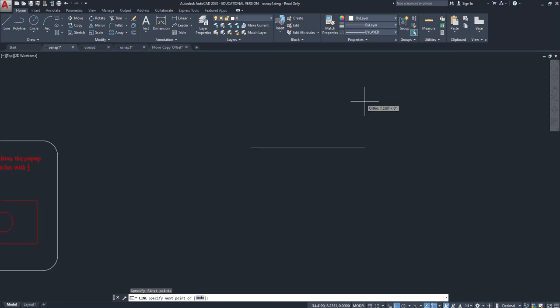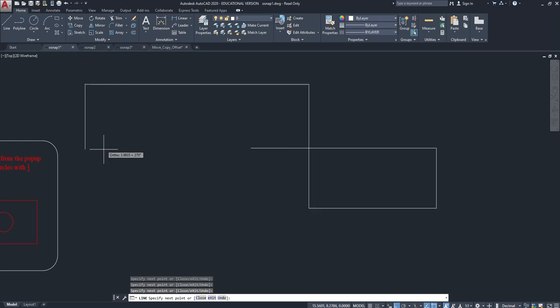Ortho means that our lines are going to be orthogonal. They're going to be perfectly straight when they're drawn. So with ortho mode turned on, I can't draw a line that is diagonal, right? And you'll notice as you move your cursor around, you see that, okay? So if I draw with my ortho on, straight lines, click, click. See, I can't come up here and click and have it be a crooked line, right? We love ortho in AutoCAD because we get straight lines with it, okay?